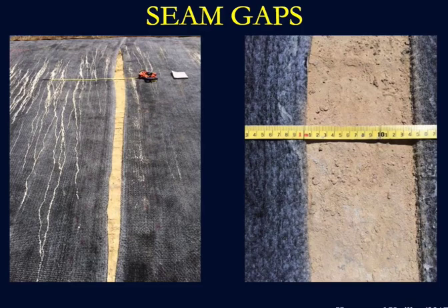And I have an image here of an example of one of those gaps. It was rather considerable. And you can see some red dots along the edges of each side of that gap. And those are placed by the manufacturer in terms of guidance for an intended overlap of these seams. And that's the state of the practice for seaming these products, is simply an overlap on the order of 200 millimeter distance.